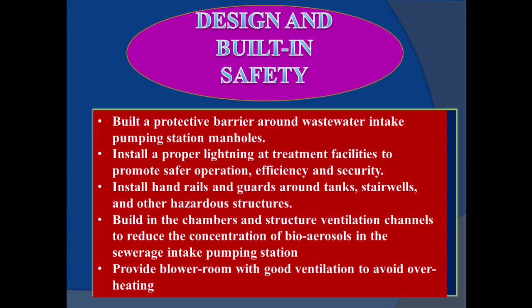For design and built-in safety, a protective barrier should be built around the wastewater intake pumping station manholes. A proper lighting should be installed at treatment facilities to promote safer operation, efficiency, and security. Install handrails and guards around the tanks, stairwells, and other hazardous structures. Build in the chambers and structural ventilation channels to reduce the concentration of bioaerosols in the sewerage intake pumping station. And lastly, provide blower room with good ventilation. This is to avoid overheating.